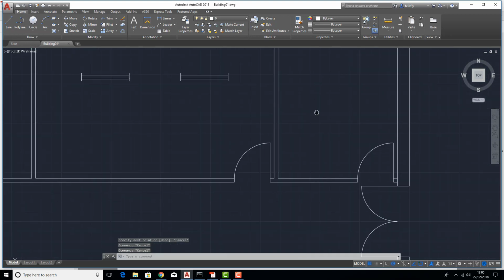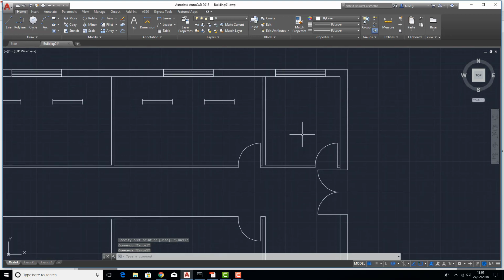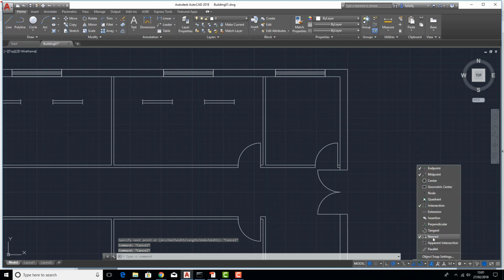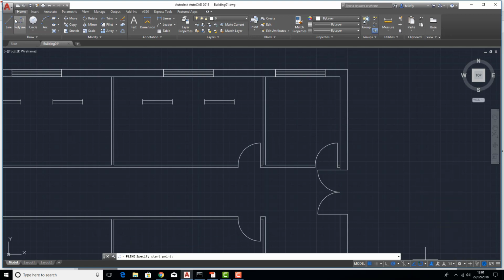If you use the nearest snap, remember we turned this snap on for nearest, if you try to do a midpoint, say, you're always going to get your nearest come on, so it's going to be harder. So I tend to turn that off after I've used it, the nearest snap. And now we can get the midpoint and